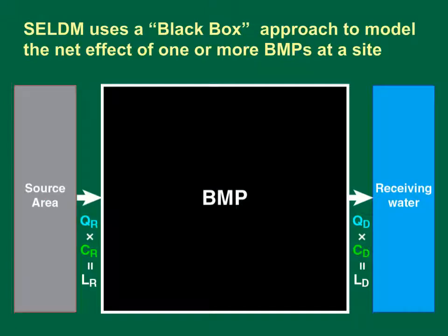SELDM uses a black box approach to model the net effect of one or more BMPs at a site of interest because there are so many complexities. Data for characterizing detailed processes over long periods of time are generally lacking, and there is great uncertainty in the application of data from site to site and storm to storm.